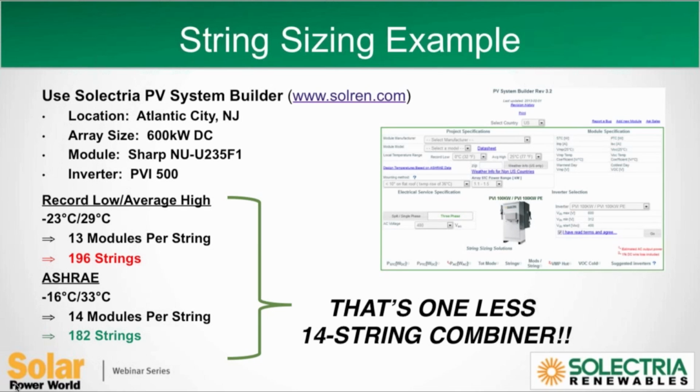The math in the background is that you're always going to get more production with a larger array feeding a fixed size inverter. And so the incremental cost of adding those panels has decreased. So you can run analysis where you vary the DC side with a fixed size inverter, and look at the effects of array to inverter ratio on your annual production. That gives you flexibility from a design standpoint.